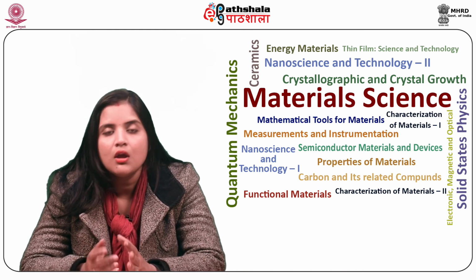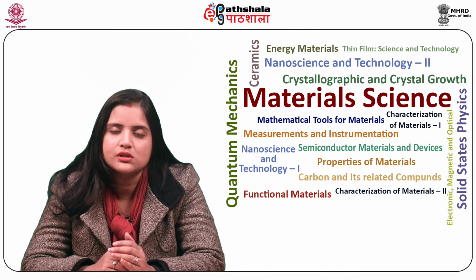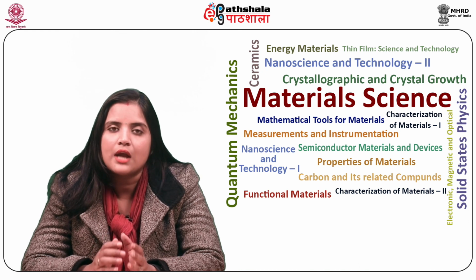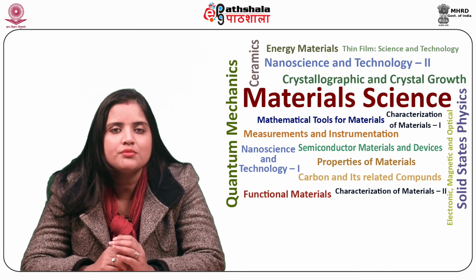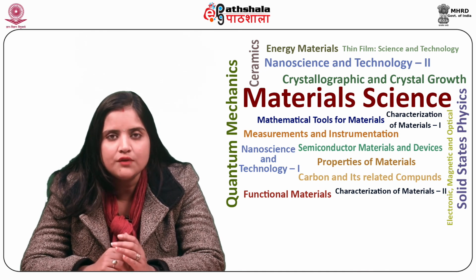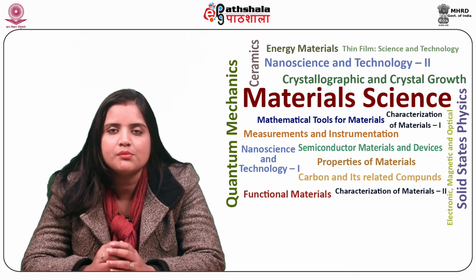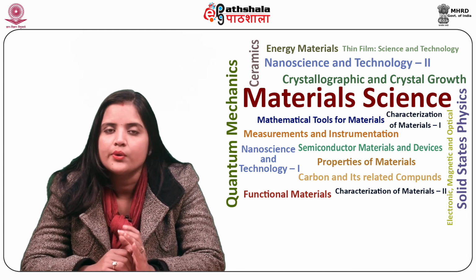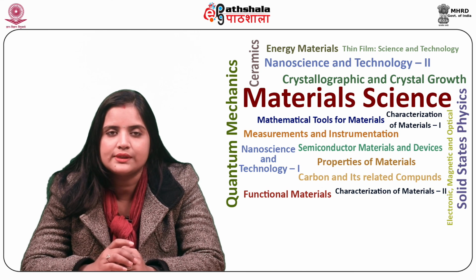Chemical vapor deposition is employed for improving corrosion and wear resistance of the materials. Typical depositions include nickel, tungsten, chromium, and titanium carbide. CVD has numerous benefits as a thin film deposition technique. The chief advantage is that the films grown by this method are conformal, which implies that the thickness of the film on the side walls of the objects is similar to that on the top. Consequently, films are uniformly coated on highly bent pieces.